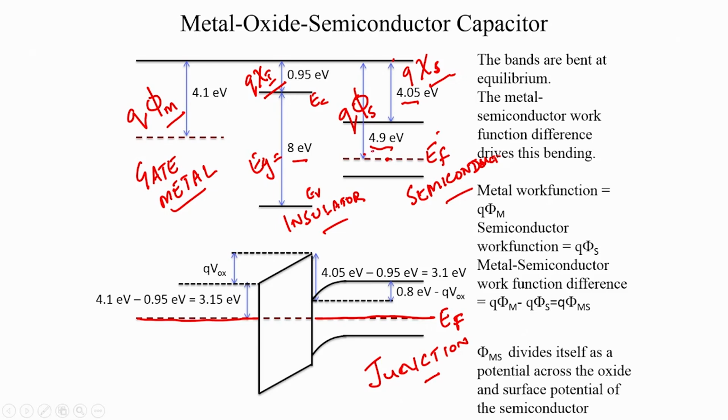So, here is an interesting question. So far, whenever we did a band diagram at thermal equilibrium, let us say it is a p-n junction or a metal semiconductor junction, we said that the Fermi levels align at thermal equilibrium, and the Fermi levels align because of the charge transfer. And very early on we looked at some very poetic analogies like water in a bucket.